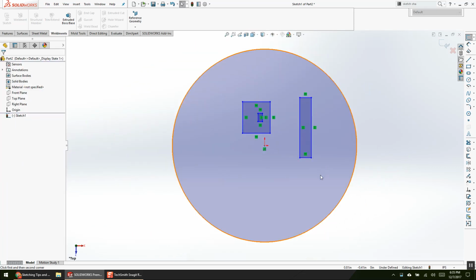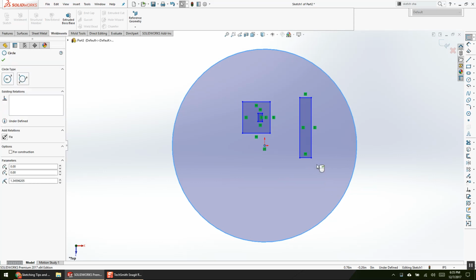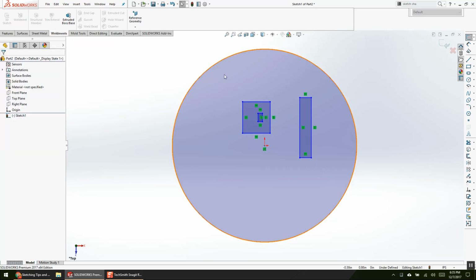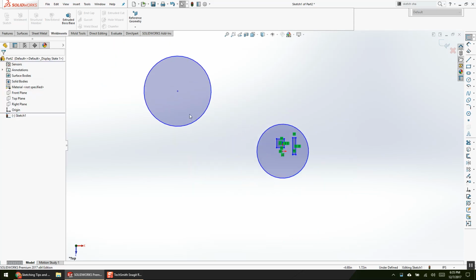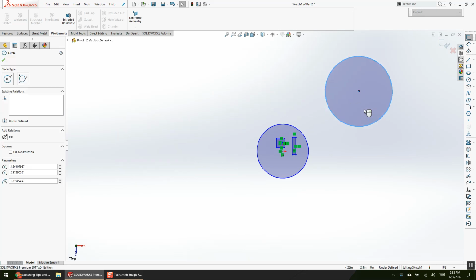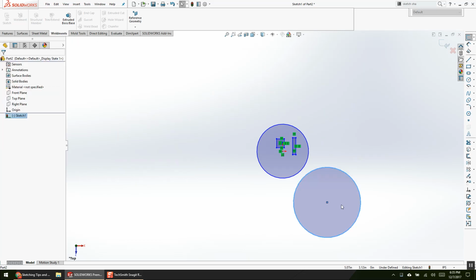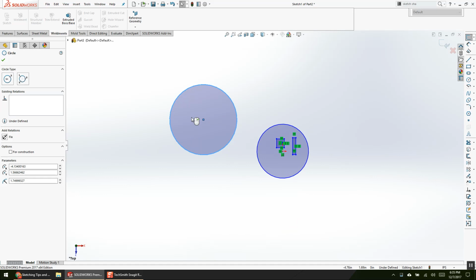But I now want to delete this stuff. So I want to box select. Oh, but you can't. With a shaded contour, you cannot box select inside of it because what SolidWorks thinks you're trying to do is move your sketches around. Which I agree is a pretty fun thing to watch and play with. It's pretty clever. But who actually wants to move their sketch on their screen?